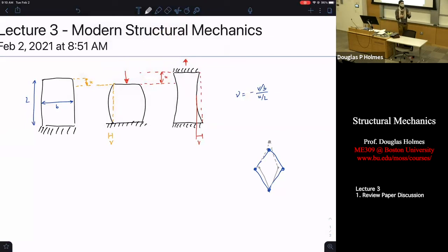And so your question is, well, how else do you do it? A foam is one way. But with the foam, what's happening is you're playing with that geometry. You're putting voids in there, and so you're altering the geometry on the small scale. Maybe not on the molecular scale, but on a micro or meso scale, not really big enough to see usually, but not small enough that it's microscopic. And what you're doing is adding defects that force it to deform like here. You're basically changing the geometry, so when you pull on it, now there are voids in certain spots, and so you see this behavior there.